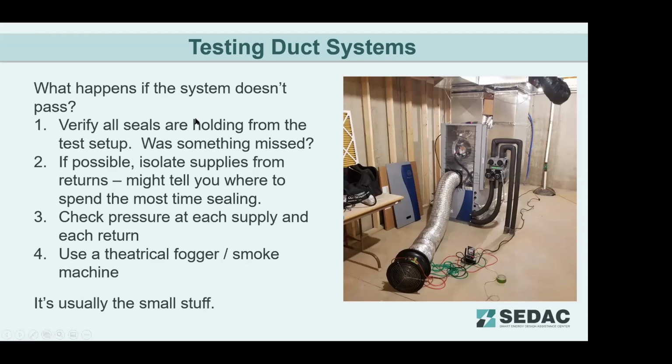So the $1 million question is, what happens if it doesn't pass the test? So as far as the tester's point of view, the first thing they should do is verify their setup. Make sure they didn't miss a supply or a register somewhere. Make sure that the tape is holding on the test.